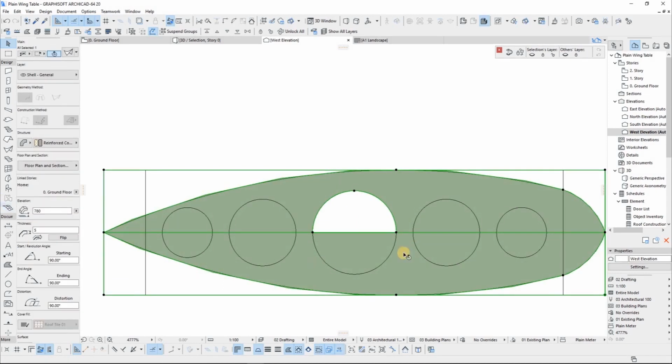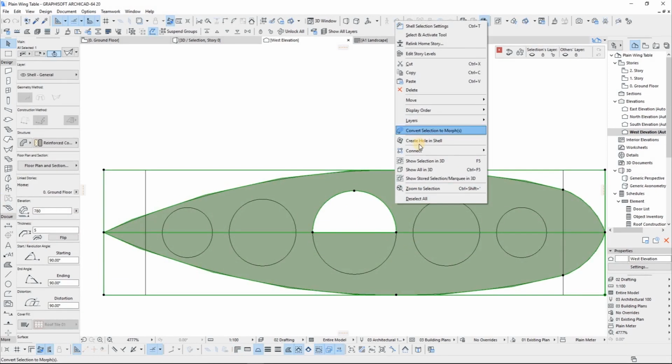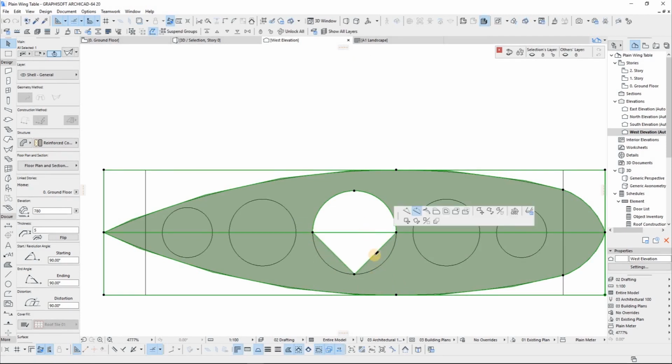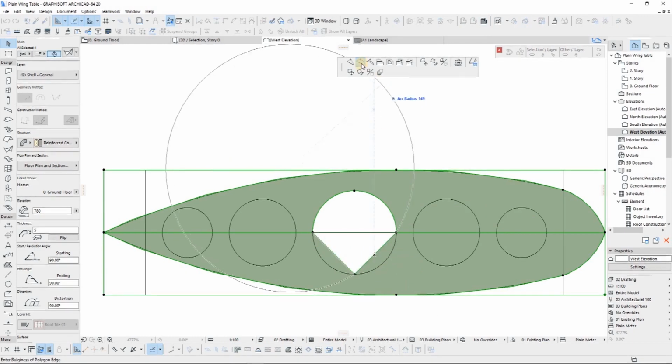Okay guys, I just want to show you something which I just did right now. Creating a hole: once you have created a hole, I'm going to create 3 points right here, so it's like a triangle using holes. With that, I can just click one of the planes inside here, select curve edge, and shape it the way I want to.